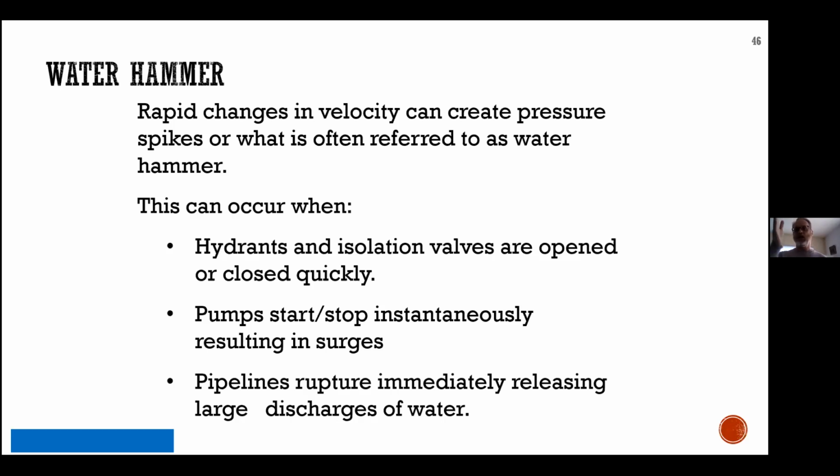So as you know, if you slam a valve shut, all of that flow, especially in a water main break, right? People's adrenaline's pumping and they want to isolate the main so the damage is minimized. You've got high volumes of water at high velocity. And if you interrupt that flow, all that energy has to go somewhere. And it is basically a rebound effect. Throwing a ball with force against a wall, that ball will come back. And it will take multiple cycles to lower that energy.